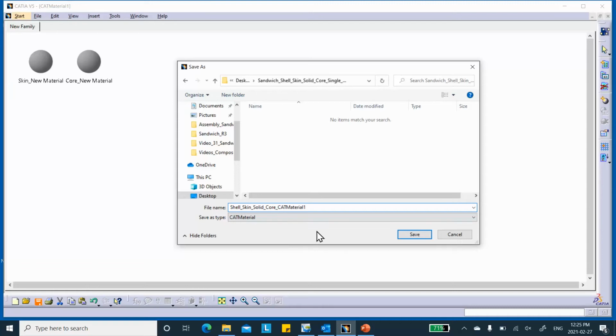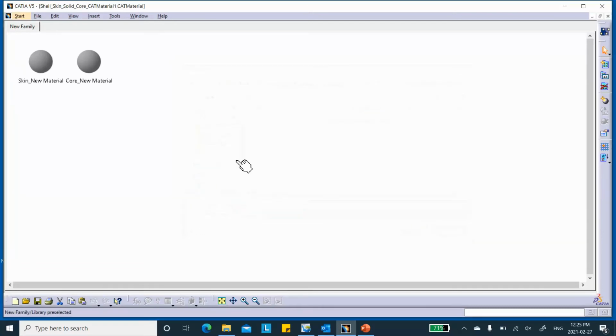Okay, before I go and do this any further, I want to remind you that when I did video 31, because the honeycomb core was modeled as a layer, there I had to specify the thickness of that layer, which was 19.05 millimeter. But here I did not, because I'm not going to be using that data for shell elements. Okay, so this is done.